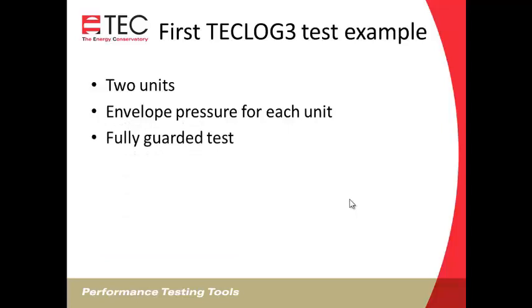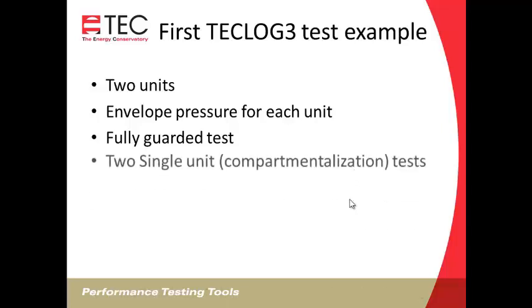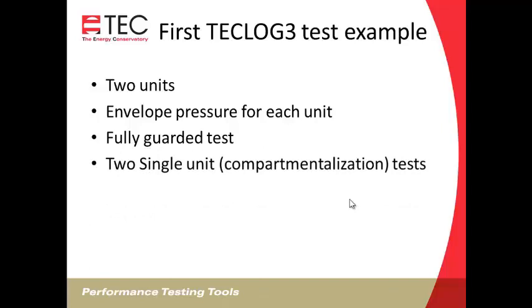We'll do a fully guarded test first, where we have the same induced pressure in both units, and then we'll do the 2 single units separately. So we'll do compartmentalization single unit tests. We'll do 2 of those, one for the first unit, one for the second unit.